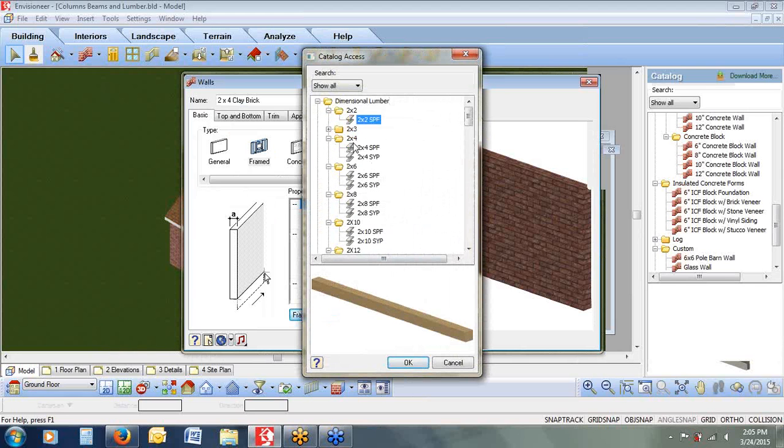So in here, I'm going to grab the 2x4 that it was looking at, but you can see I can grab any size of member. What I specifically want to look at for this member are the properties behind it, because a 2x4 can come in many different lengths. And I want to make sure that it's going to be grabbing the right length for this purpose that I need it for: my studs, my top plate, my bottom plate, the sills. All of the different uses of this 2x4, I want to make sure that all of the lengths that I can order are sitting inside that 2x4.